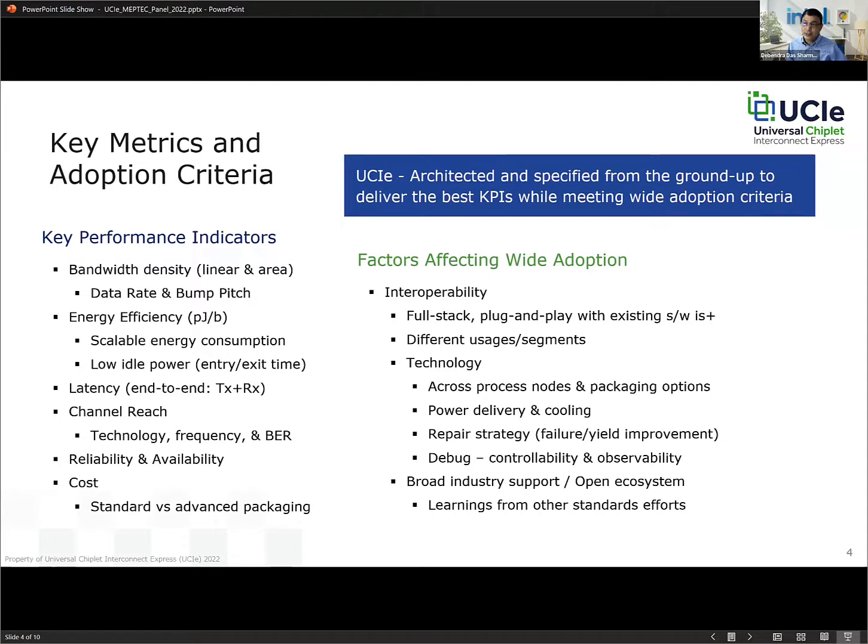So, okay, we define the bus, but what does it cover? Is it a full stack? Can I design something and plug it in the same way I can do today with PCI Express or CXL, right? It's a well-defined spec, end-to-end everything. You just design your part. You don't have to know who is designing the other side, right? If you look at something like the PCI-SIG consortium, it's 900 member companies. It's impossible for two sets of companies to be talking to each other and designing a part that will just work between them, right? So it's a fully open ecosystem with everything being defined very precisely.